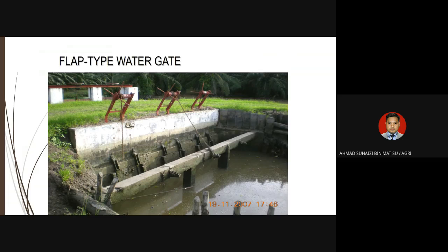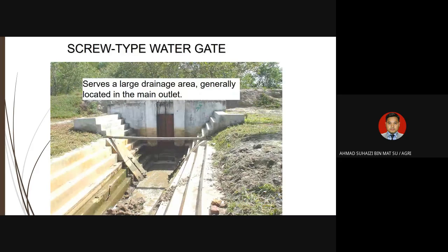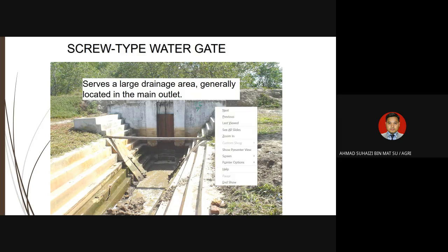Yeah, so in some areas, here in this location, salt water intrusion sometimes happens. So you need to design a proper gate, a water inlet and water intake. Yeah, so here is the main outlet for the water to go from the farm outside, to the shore or sea, and also prevent the salt water from coming in. Okay, you see, here is the gate to control the water level here. There is a steering wheel on the top here, and also there is a bund